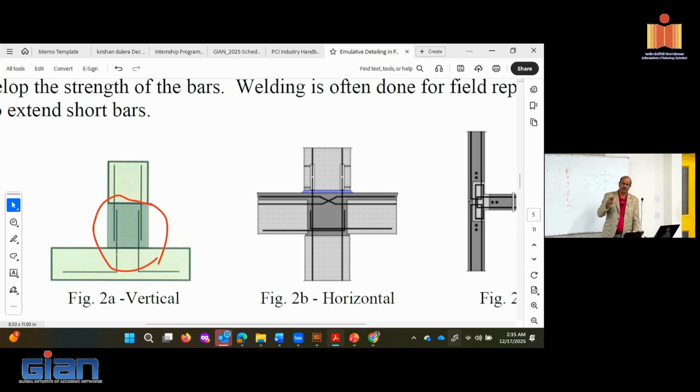I just want you to see what people have thought through in terms of how to establish a connection. This is a precast member, this is a precast member, or it could be cast in place with the rebar sticking out. You bring the column down, and you cast that joint. When you establish that connection, obviously this has to be temporarily supported until the concrete is cast and cured, which may not always be easy.